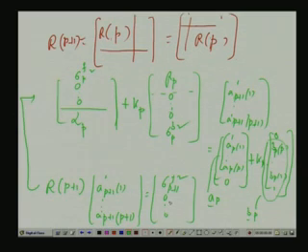Now, you see one thing, there are two vectors on the left hand side here and both the vectors have some non-zero quantities on the top and the bottom, but in the middle there are zeros. So, at least I am able to get all the zeros here. 0 plus Kp times 0 is 0. So, the zeros are matching. In the last row, alpha p plus Kp times sigma p b square, that also must be equal to 0. So, solving that I get a Kp. So, that means what is Kp? For the last row, I know what should be Kp. So, I can choose a Kp like this, that alpha p plus Kp times sigma p b square equal to 0, so that the last equation is satisfied, which gives rise to what?